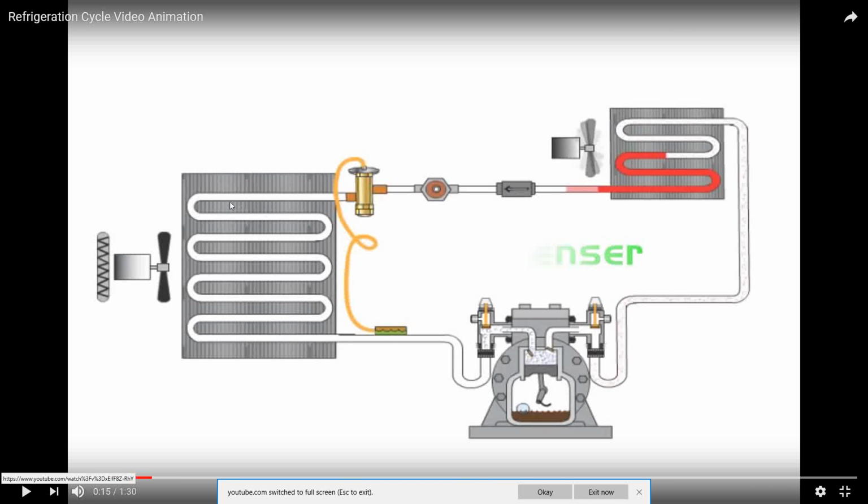So now with only these three components, evaporator, compressor, and condenser, you can see this cannot form a cycle, because if this high temperature and high pressure liquid goes to the evaporator again, it cannot absorb the heat from the indoor environment because the temperature is high. Maybe the temperature is just higher than the environment you want to refrigerate.